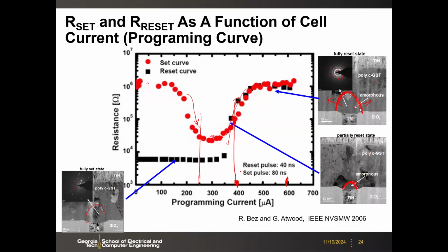So that's why this is unipolar switching. It's not the positive current or negative current, positive voltage or negative voltage. This is by the amplitude. Because no matter if current flows this way or the other way, I squared R is about Joule heating. It's amplitude, not the direction of the current. This is a unipolar switch. Okay, this is different from RRAM or MRAM we're going to talk about, or even FE ferro. That really depends on the voltage direction or current direction.